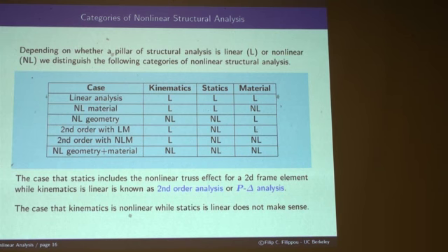Don't ever tell me the displacements are small because they're 5 inches, because I'm just going to grab a gun. 5 inches means something to you, doesn't mean anything to me, and if the structure is 300 feet tall, 5 inches may not be that big. Right? I don't know. I have to have a ratio, 5 over 300 feet. So 300 times 12 will be 3600, 5 over 3600, actually it may be very small. All right? But 5 inches over 10 feet may be large. All right?